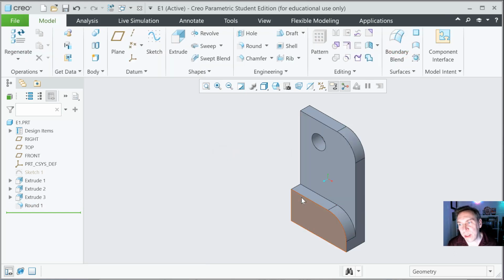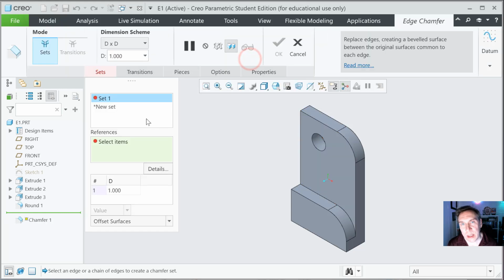All right, let's put in some chamfers here and here. So find the chamfer tool, and the distance, like see here, there's distance times distance. And on a 90-degree angle, if the distances are equal, it will automatically be 45 degrees. Or you could go 45 degrees by distance, or a specific angle to distance. So maybe you want it to be 16 degrees at 0.25. You could set that up there. A lot of nice options. We're just going to go distance to distance because it's easy, and